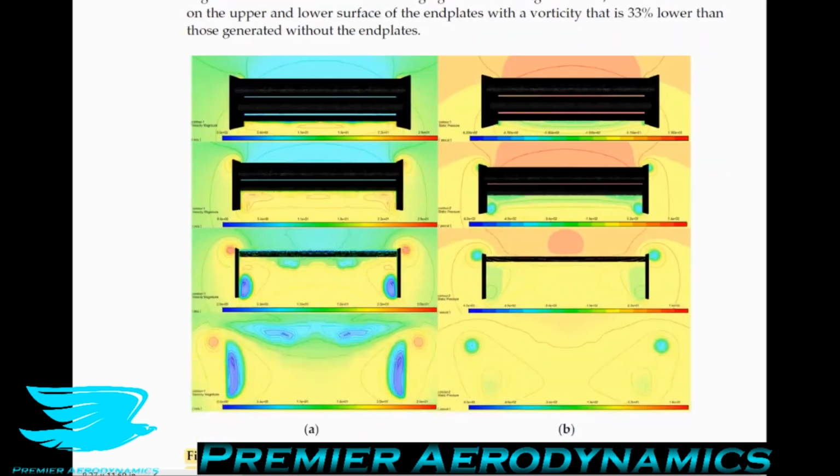So figure 8, they say it can be seen that the end plates to this structure fulfill their role by preventing the appearance of large wingtip vortices on the edges of the wings and delay their appearance, thus improving the ability to generate negative lift of the 3 elements belonging to the rear wing.